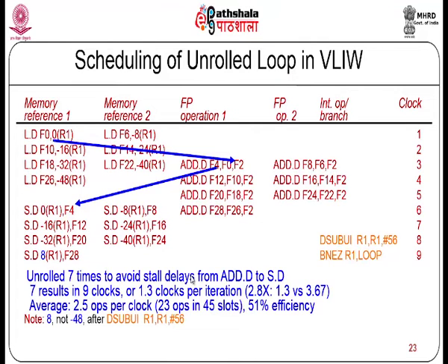In the first clock cycle, the first bundle consists of 2 instructions in our example. The second bundle also consists of 2 instructions, but if you look at the third bundle, it consists of 4 instructions, where you have 2 loads and 2 adds, and only the integer slot goes vacant. So as you are able to identify parallel or independent instructions to fill into all these slots, better utilization of the functional units will be achieved.